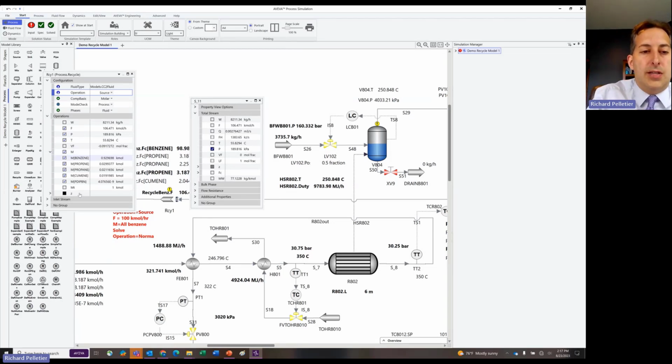So when I do this, I want to have these two windows open so that I can see, okay, I changed this value here. What impact does that have on this value here? And are they close? And my goal is to get these close enough so that I could switch it over to tear and then to normal operation. I'm going to talk about those in more detail in a second. All right. But the idea behind this is that you are manually working with the recycle, basically coaxing it into the solution that you need it to achieve.